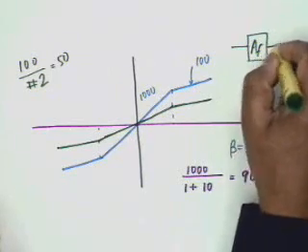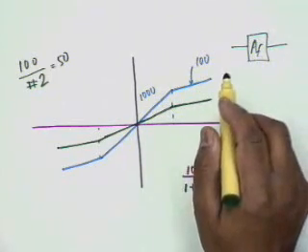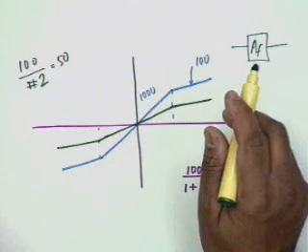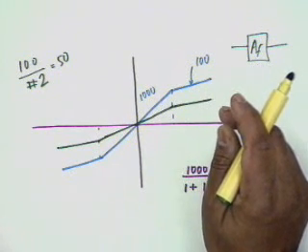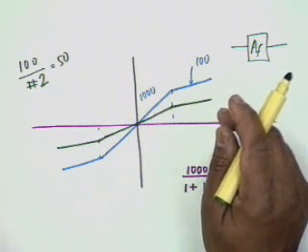Gain is reduced by a factor of, in this range, 10 or 11? 11. The gain is reduced by a factor of 11. Now one can argue that this feedback amplifier that you have, AF, you have reduced nonlinear distortion by introducing negative feedback, and the factor is 11.